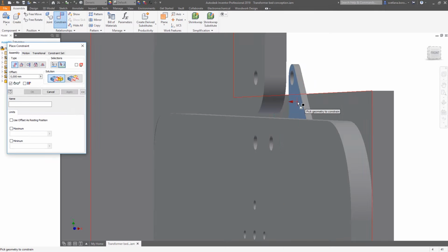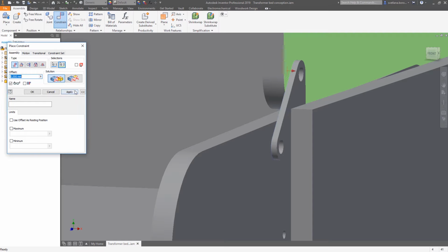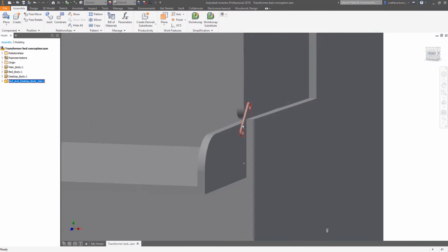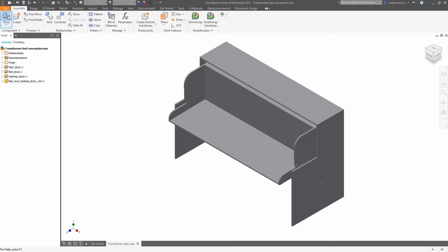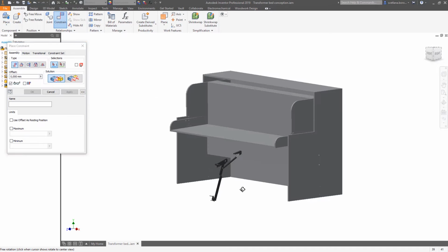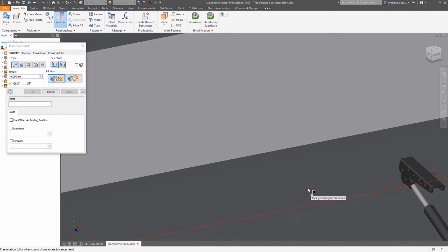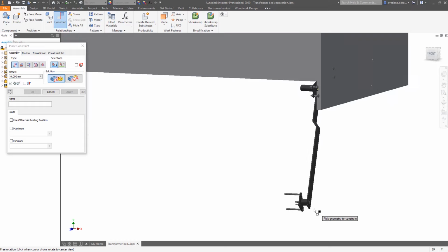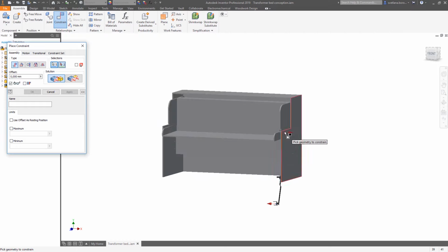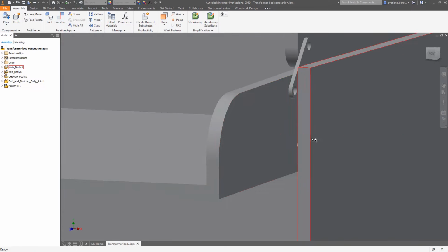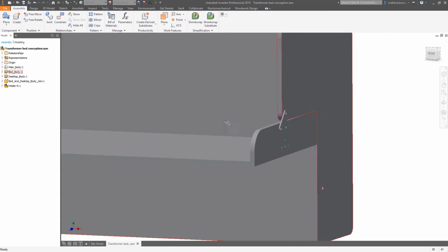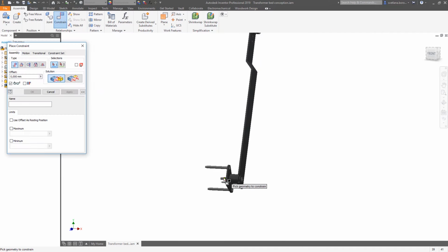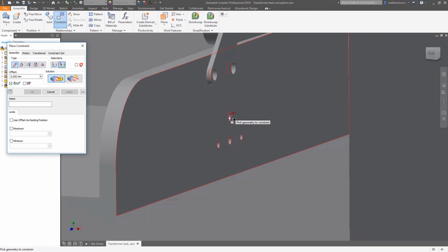Okay, so once the component is in place, we can place the hardware item. In this case, there will be a detailed mechanism which can be placed in the right position using constraints. Since it's quite a complicated mechanism, we must apply some constraints here and there to see if everything works the way we expected. This module can be set to be flexible, and it makes it possible to check kinematics.